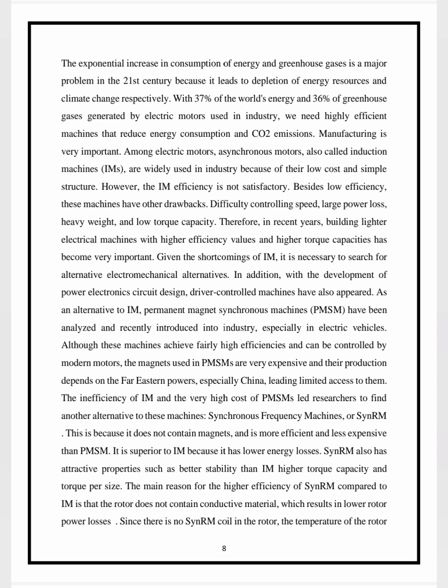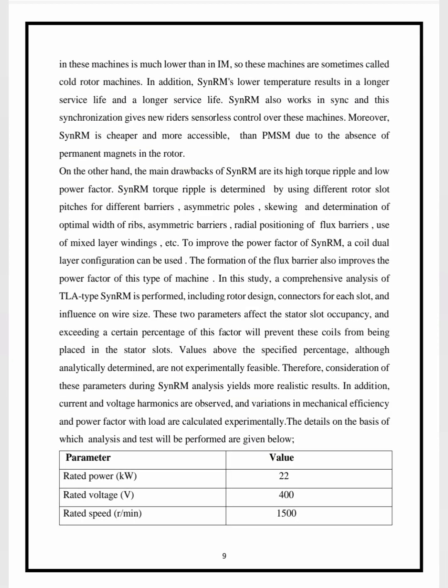Since there is no coil in the SynRM rotor, the temperature of the rotor in these machines is much lower than in the induction motor, so these machines are sometimes called cold rotor machines. In addition, low temperature results in a longer service life, and longer service life means that it is also eco-friendly.